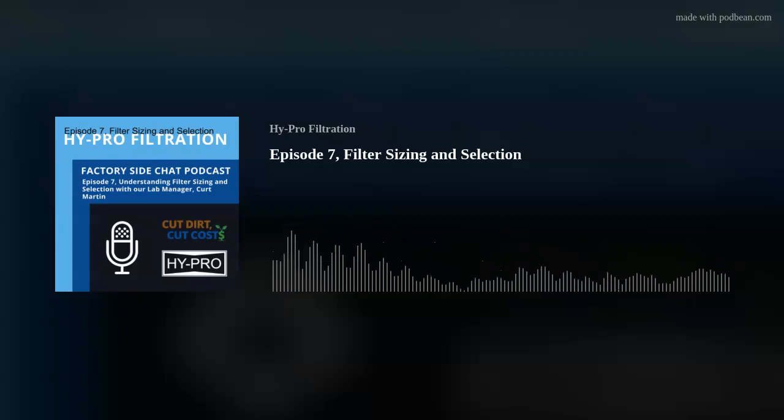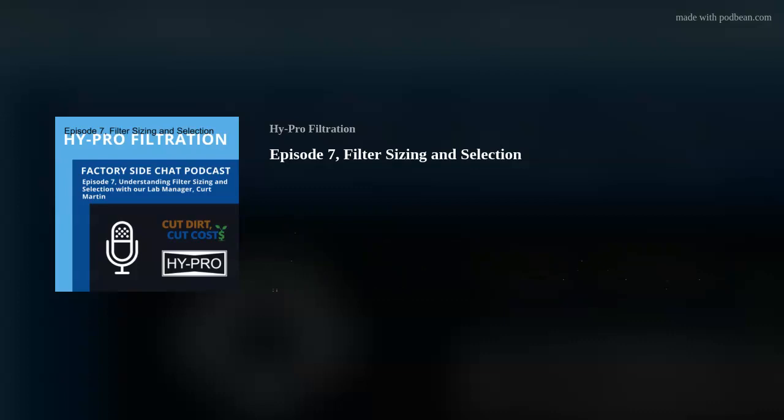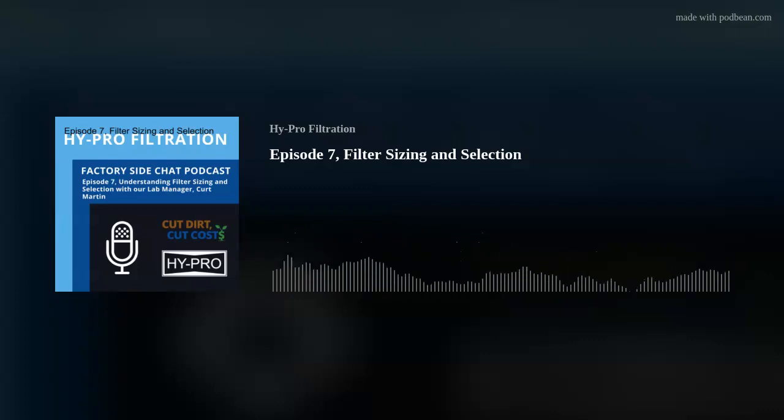And with high collapse elements, you're going to have thicker center tubes. The pleat packs are assembled a little bit differently on the support mesh that's used. And those are typically rated for 3,000 PSID, where the low collapse elements are typically rated for 500 PSID and less. And with a high collapse filter element, we are going to be using a blocked bypass, or no bypass valve, in the system. Correct.